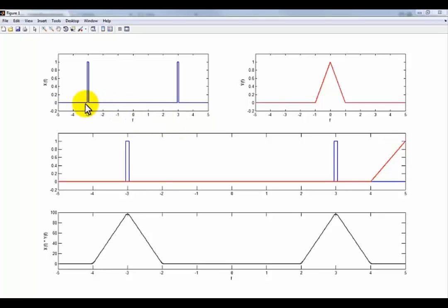So this is just a quick reminder of the convolution. When we multiply the signal on the left by the signal on the right in the time domain, we convolve them in the frequency domain. And a simple way of thinking about it when they're just delta functions is you're going to take this spectrum here in the red and you just plunk it down wherever there's a delta function. You can look at this again and see how the convolution is actually done, but as long as you remember I just take this and put it down where each delta function is, you'll have a good idea.